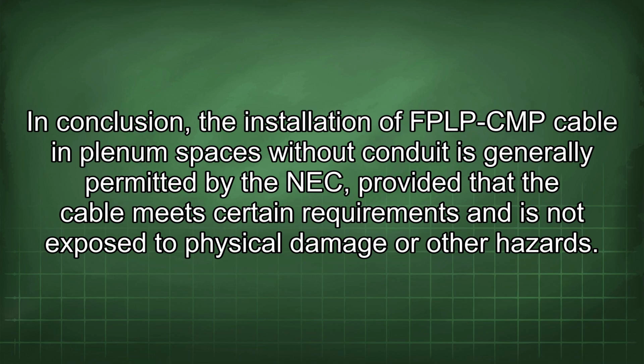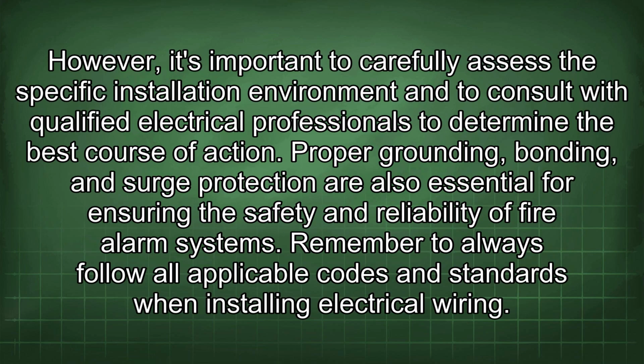In conclusion, the installation of FPLP CMP cable in plenum spaces without conduit is generally permitted by the NEC, provided that the cable meets certain requirements and is not exposed to physical damage or other hazards. However, it's important to carefully assess the specific installation environment and to consult with qualified electrical professionals to determine the best course of action. Proper grounding, bonding, and surge protection are also essential for ensuring the safety and reliability of fire alarm systems. Remember to always follow all applicable codes and standards when installing electrical wiring.